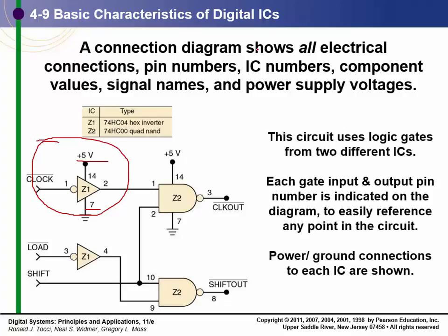When you bring the circuit into Ultiboard, you can start laying out where you want the ICs to be on your board and how you want to draw the connections on the board. So it provides a path from your circuit drawing in multi-sim to your PC board layout in Ultiboard.